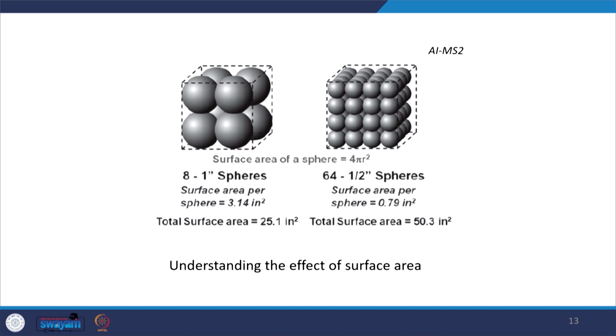So here you have to remember that as the nominal maximum aggregate size in the aggregate gradation decreases, the surface area increases. Many times people say that surface area increases. So try to remember it in this form, that the specific surface area increases, and specific surface area is the surface area per unit volume, all right, and therefore more binder is required to sufficiently coat the aggregate particles.